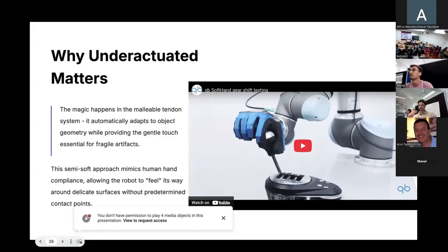So it can mimic human grasping, but at the same time save us a lot of trial and error, because if it was a fully dexterous hand with multiple degrees of freedom, the RL would spend a lot more time trying to explore each configuration of the hand, and we are not interested in that. We're interested in having human-like behavior to handle the pieces like a human would.